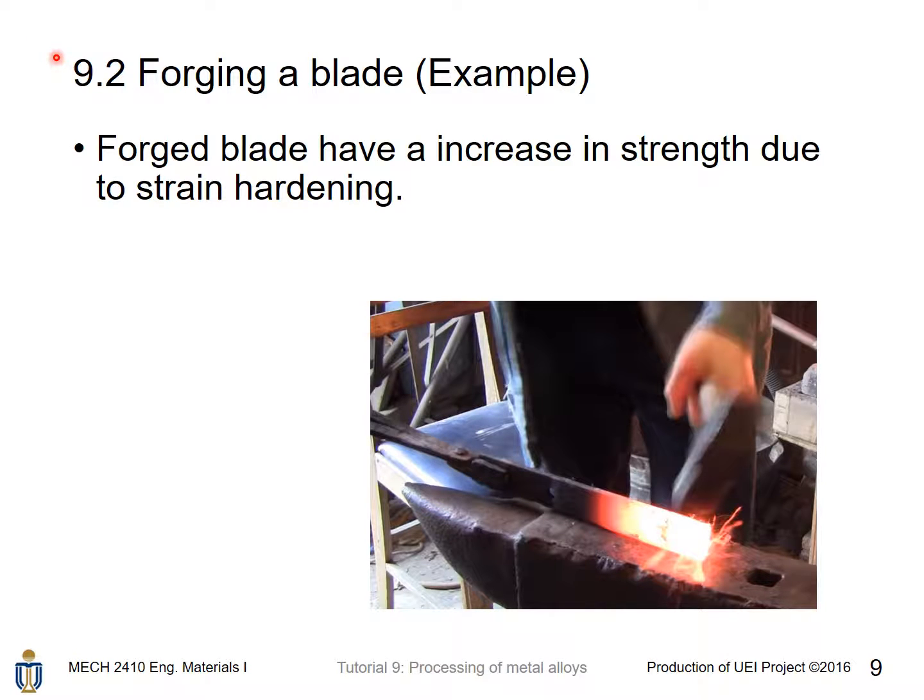Well, this question can be explained if we consider the nature of these two methods. In the forging process, there is dislocation strengthening. If you hammer a workpiece, you will cause a permanent deformation within it, which basically means that it is experiencing strain hardening and dislocation hardening, both of them.